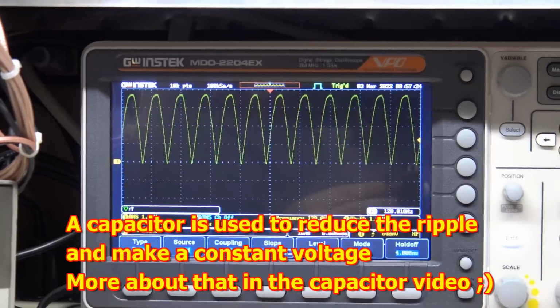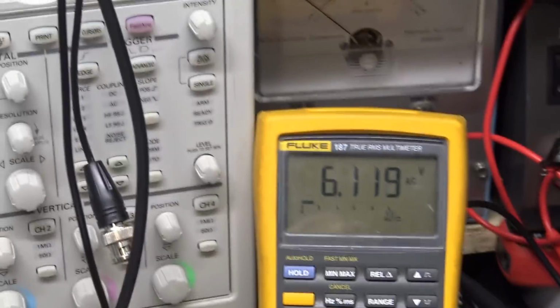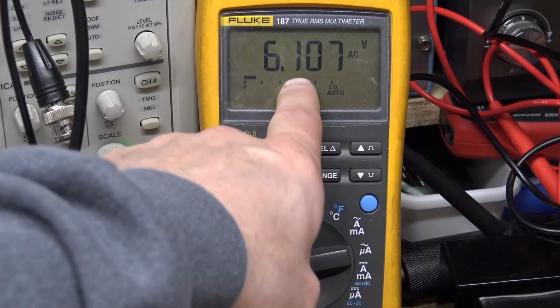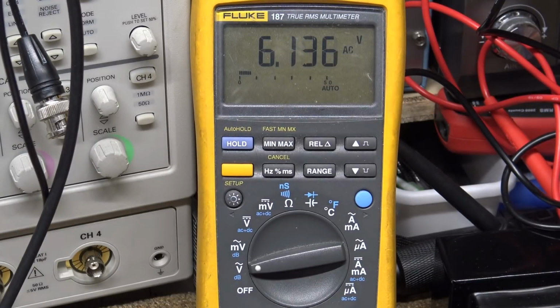And if we look at it on our meter, this is our true RMS meter once again. You can see it's showing about 6.1 volts RMS AC. Now, the measurement on my scope is not going to be correct because I had to use a special device called a differential probe, so my scaling is off. I would have to change that, and I didn't feel like doing that this morning.